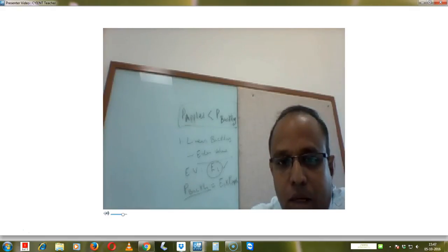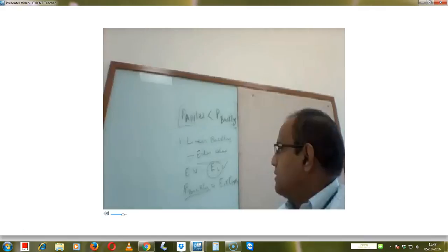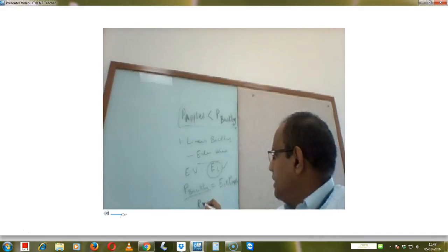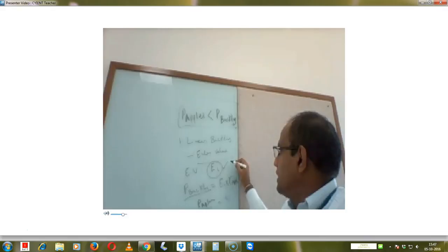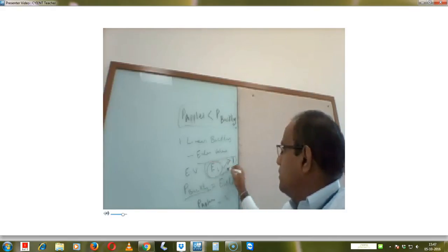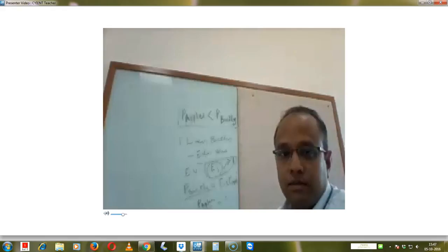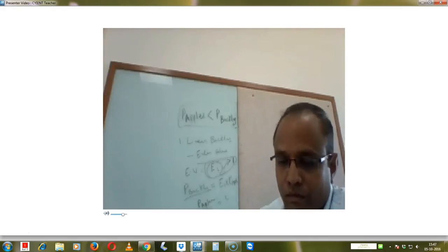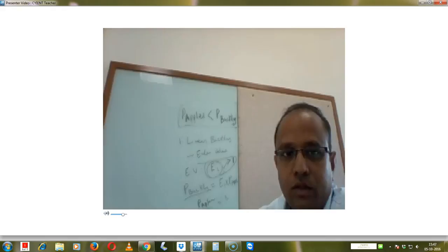So in this analysis, the magnitude of the resultant buckling load factor must be greater than the applied load factor. Okay. So the applied load factor is P applied by P applied. That is one. So definitely E1 should be greater than 1. Eigenvalue should be greater than 1. Definitely.